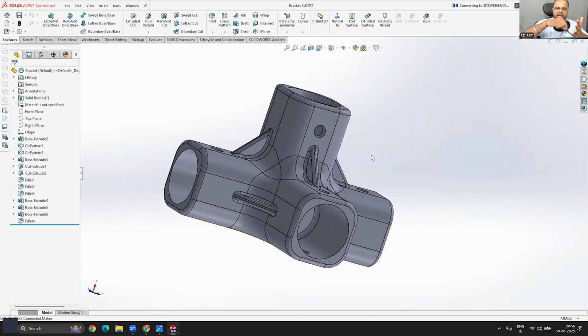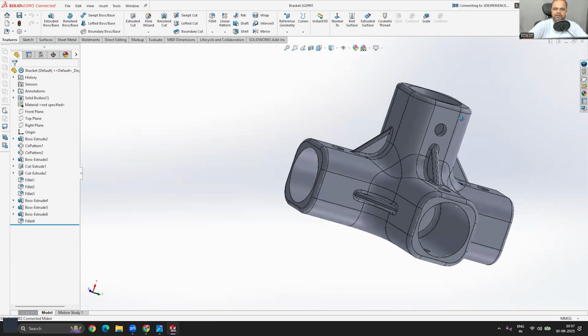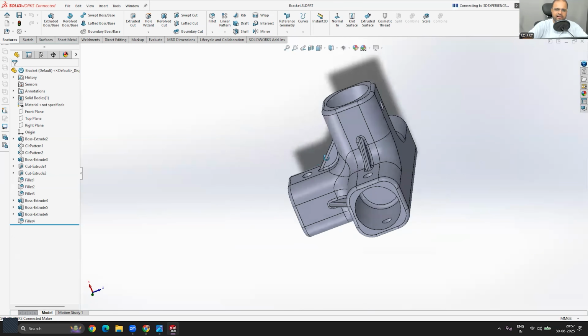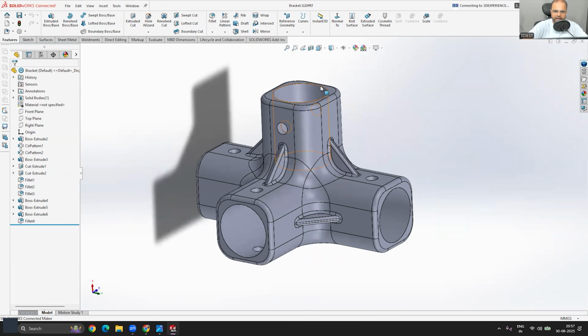So panning is like moving your complete canvas here and there. Let's say you're making some drawing on a sheet. You can move the complete sheet using the pan tool, and that you can activate using Control plus the middle scroll wheel of your external mouse. So that way you can access your model from different angles and different sides. I hope it's clear up to this point, everyone.